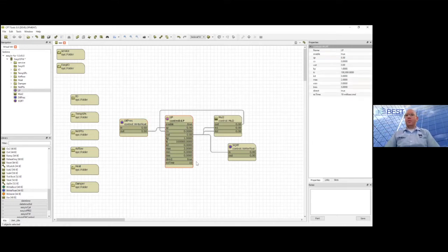You have to set it to indirect, and it will cycle through and figure it out for us. But we have to use an exceptionally small KP and a surprisingly big KI, integral factor. Otherwise, it just creeps up on it and takes absolutely forever.